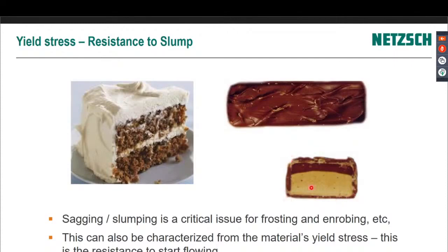So in the old days, you'd get a little meniscus, if you like, of chocolate on the bottom. They called it feet, and they said they wasted millions of dollars worth of chocolate per year by doing that, where they were trying to get the stand-up properties on the top. So they changed the emulsification process and used a rheometer. At that time it was from Bohlin, and they reformulated to give a higher yield stress. And so that shows you its stand-up properties.